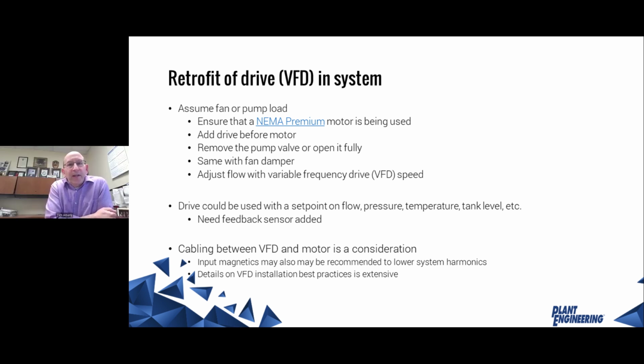So what I'm going to talk about is a retrofit, or the installation or addition of a variable frequency drive into a system. We've already talked about the different types of loads, and one of the things we made very clear is that we're focusing on variable torque loads, so in this case, a fan or a pump load is perfect. It could be a number of different compressors as well. There are some best practices that we would recommend.